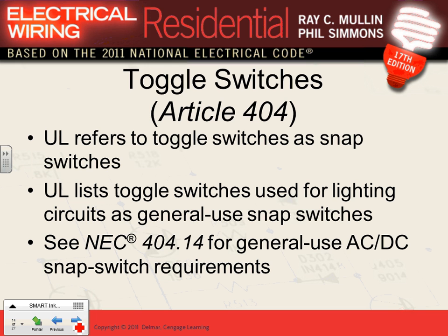Okay, the second one, there's a whole article that talks about receptacles, guys, and switches. This one is 404, which talks about switches. They call them toggle switches, the ones that you see in the wall here, also known as snap switches. Used for lighting, general use snap switches, we use them for lighting.